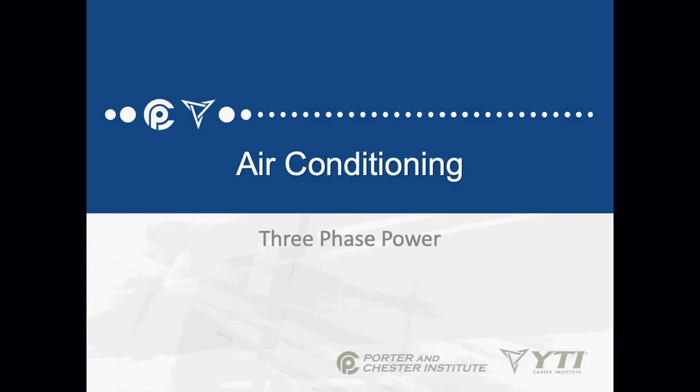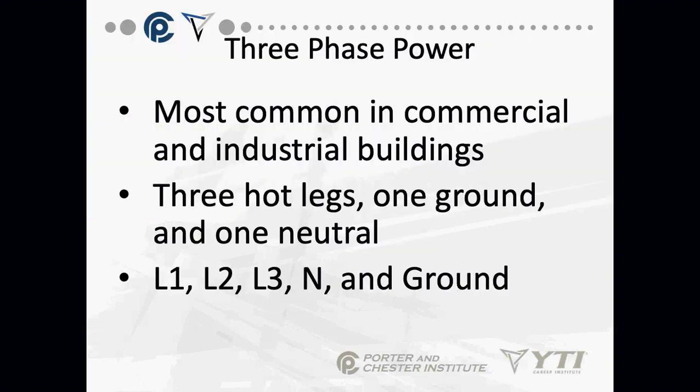Now, will you see capacitors installed on a motor that's on a three-phase system? Yes, because I can run a single-phase motor off of a three-phase power source. We'll talk about that. But primarily, three-phase power is most common in commercial and industrial buildings. You have three hot legs, you will have one ground, and you might have a neutral. Do not count on having a neutral.